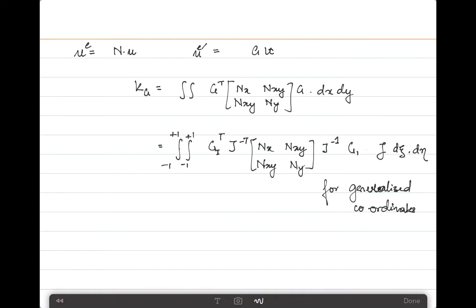This is a standard formulation for a plate element. If you think about it carefully, we have been following the same general description for the kg for each of the element. It includes the derivative with respect to length or area of the shape functions, along with the description of the load in between.